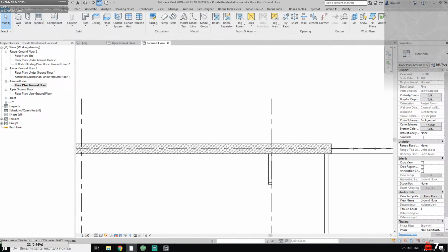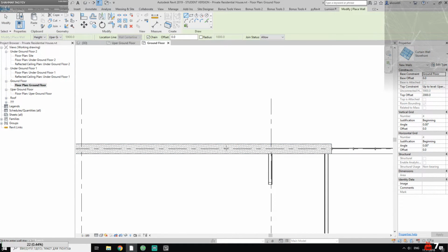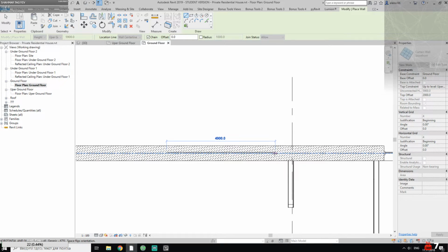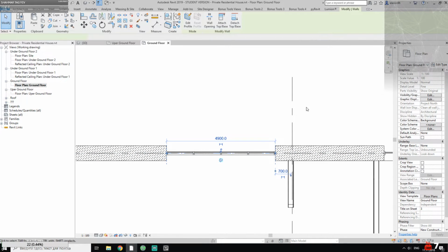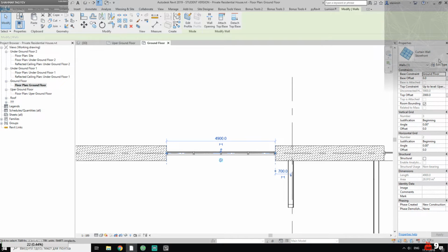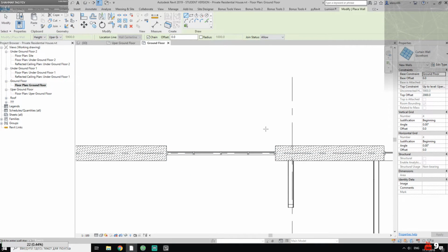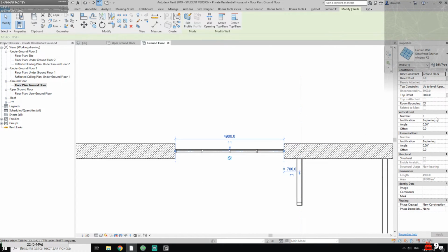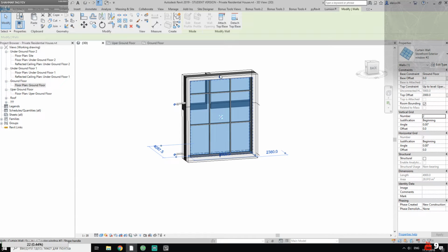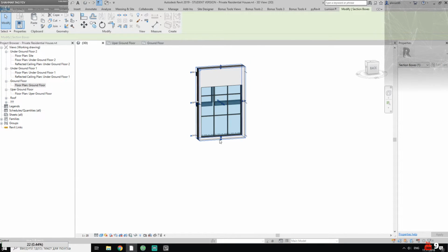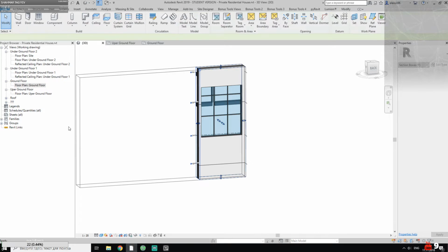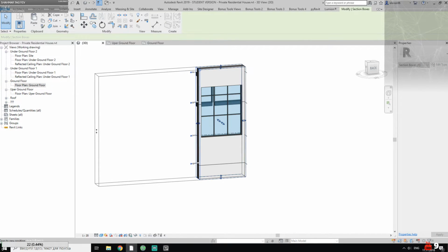Anyway, let's choose the wall. Again, storefront, and let's create our wall here. We need only 3 of that. Let's choose the other type, that one, and here we're able to change to 3 panels, like this. I say it's 3 panels. Oh, sorry. If you want 3 panels, you should write 2 panels. It's a kind of strange thing, but you should do that. And of course we have the one huge window, and we will change it now, like this.